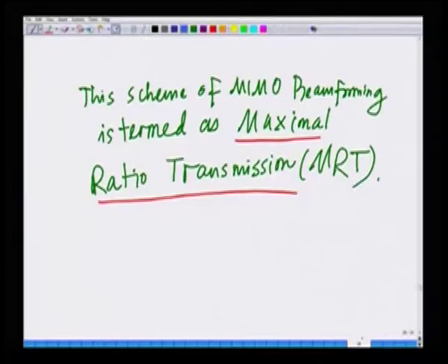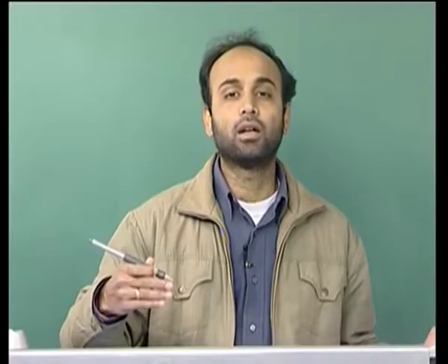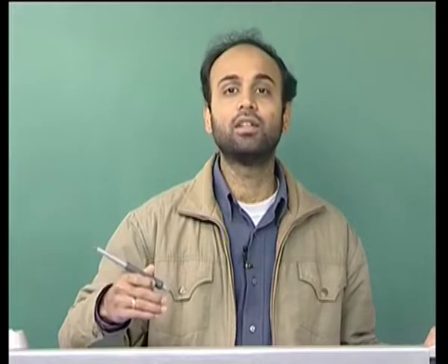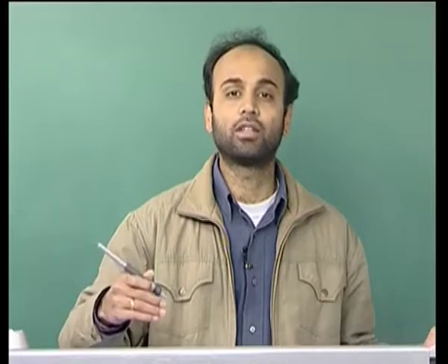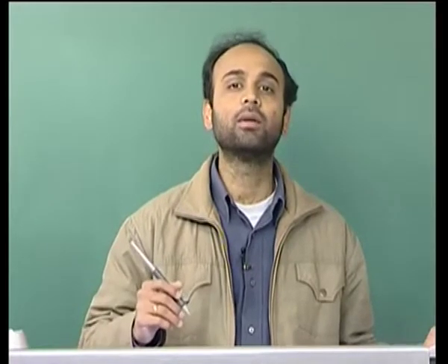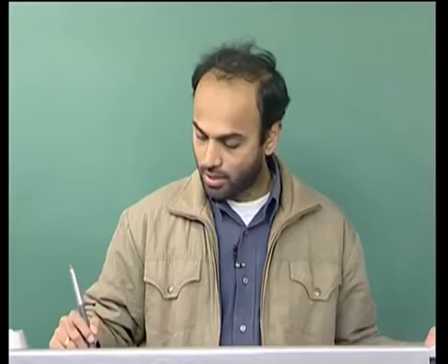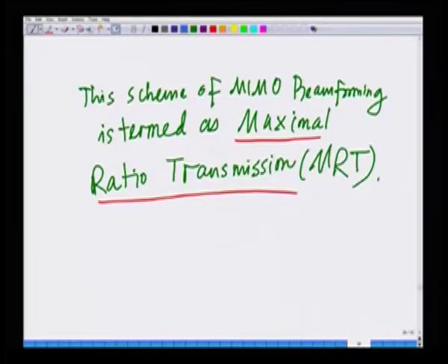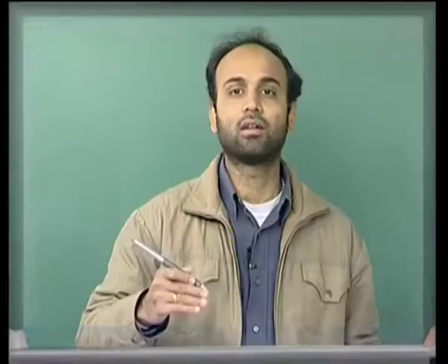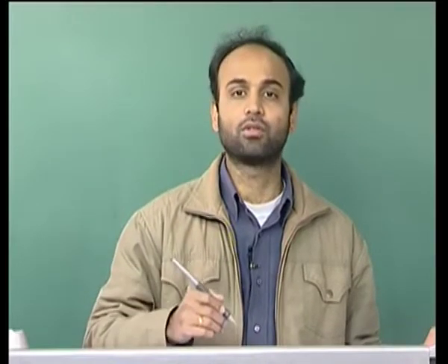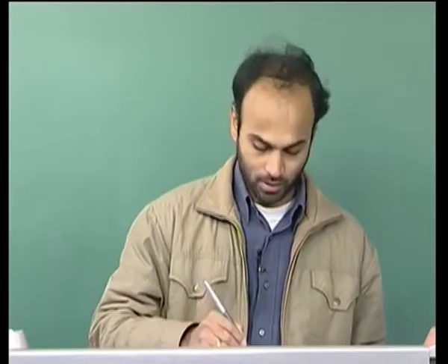Further, we said that this scheme is maximal ratio transmission, termed MRT, which yields the channel gain corresponding to the largest singular value, or the strongest mode in the MIMO channel. With that, essentially that concludes our discussion of the MIMO module. Let me start by summarizing the MIMO module, and then I will continue with the next module in this course on 3G, 4G wireless communication systems.